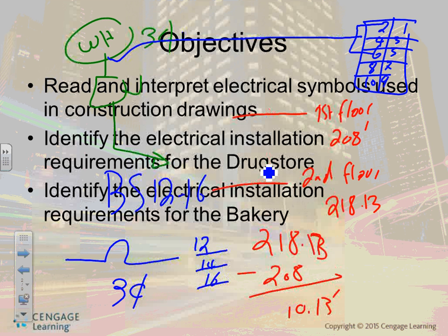Okay, it doesn't matter. So if you guys look at the meters, and then do me a favor, look at the generator. Can you see it on the right side of the riser one line diagram? There's a generator feeding an auto transfer switch, right? You see where it's a little gen? It's feeding owner equipment, and one of them is feeding elevator control, and the other is elevator equipment. This is for your emergency.